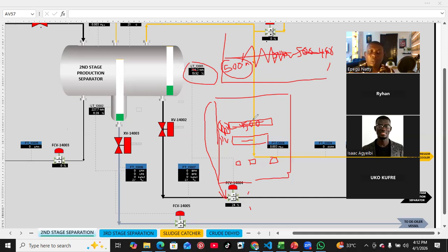controlling the system. Now, this can affect if the programming is not right. So which is why by the time they are doing commissioning of your DCS, they check all these parameters and confirm that the auto mode is working perfectly, right? So if not, if you are on a real plant, even though you put it on auto mode, you still have to be monitoring what is going on, right? You go to the air screen, you come back, you check if the level is okay, right? So that is that for auto mode.